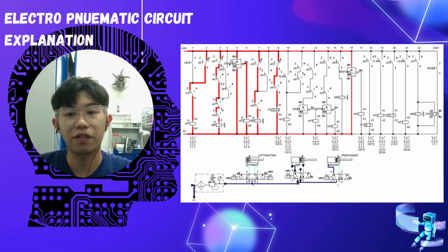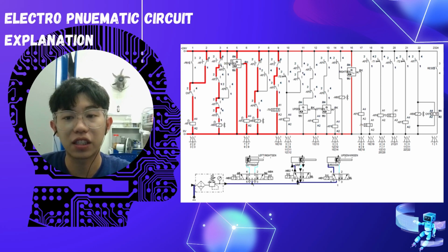When the down sensor is actuated, the current will flow through relay KF2. The normally open contact of relay KF2 will close, leading to the energizing of valve solenoid MB2. In the pneumatic circuit, the grip will advance.